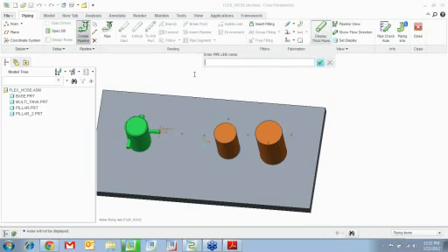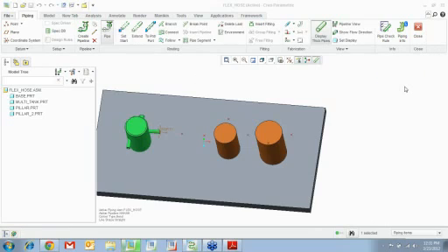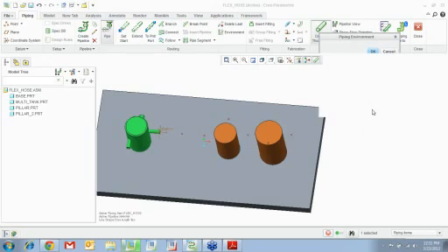You want to go ahead and set it a name. I want to use the line start. I go into environment and I want to make sure that, hey, you know what, my line start is flexible. I can set a length and say this is how much I want the length to be, or I can go free, okay, and say okay.